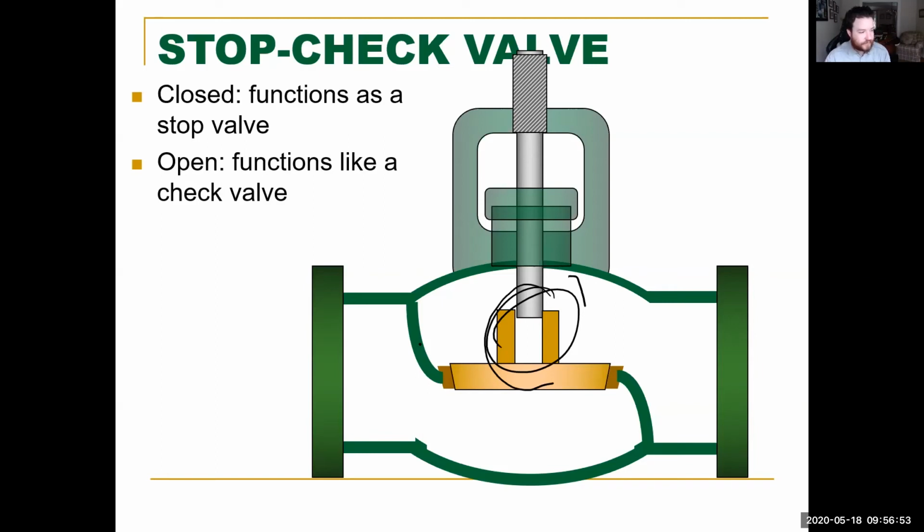They're connected in the sense that this stem right here will never go far enough away that this seat, this piece right here, will become detached from it. You'll never get to the point where it comes out of the stem so far that this will move and now it will never become realigned. The stem will always be the guide for the disc.